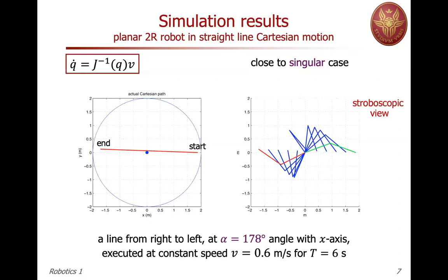See, we are 2 degrees off now, but what does 2 degrees mean in terms of Cartesian position? Now, 2 degrees is a small angle, so you can approximate sine of an angle with the value of the angle itself. You express the 2 degrees in radians. So this is about 1/100 of a radian. The distance is 2, so the radius is 2. So we are about 2 centimeters above the origin when we are crossing the origin. This is the path, okay?